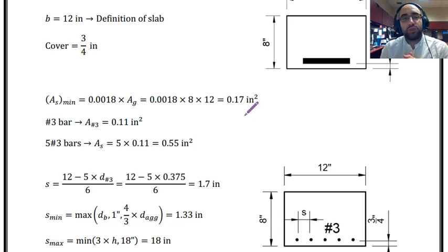For dealing with that issue, it is better to distribute the reinforcement with a larger number of bars. I'm talking about more bars in the section instead of having just a few bars. Having more bars and distributing the load between more bars in the section is better in terms of the stress distribution and a uniform load distribution between the reinforcement and concrete.